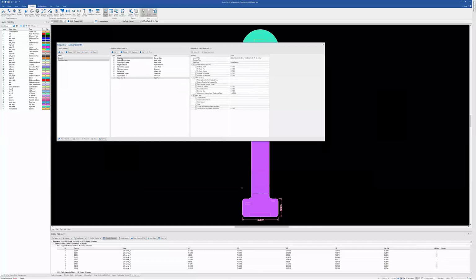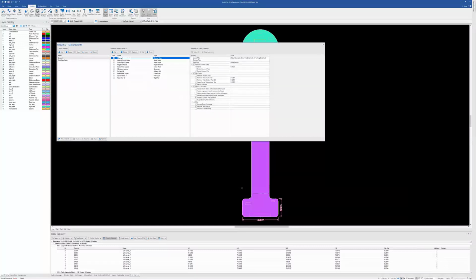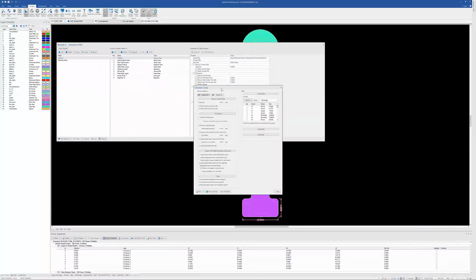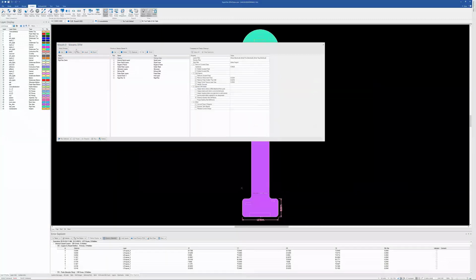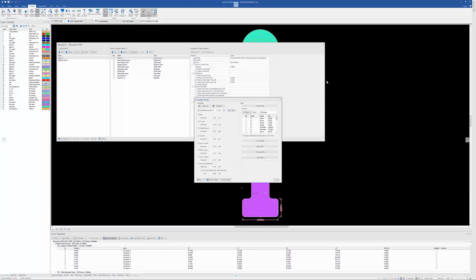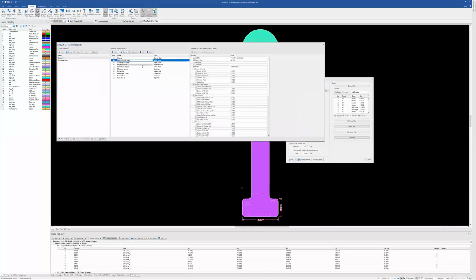So, when I'm on cleanup, you see this dialog here. I could actually run just the cleanup by itself. Or if I wanted to run an annular ring check, for instance. Now there are annular ring checks in both the internals and the outer layer parts of my checklist over here.